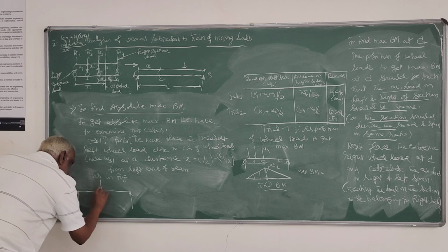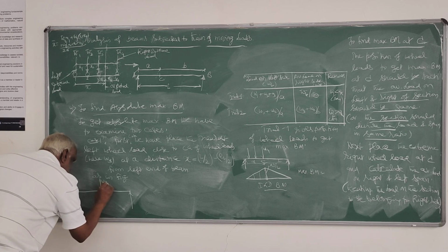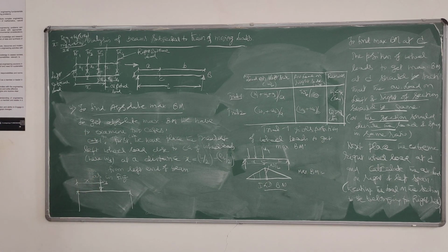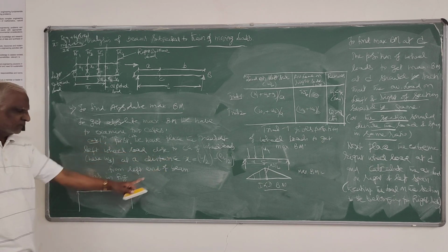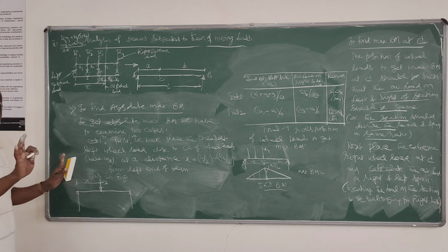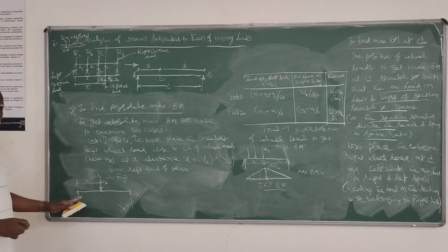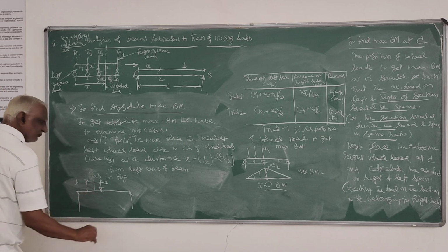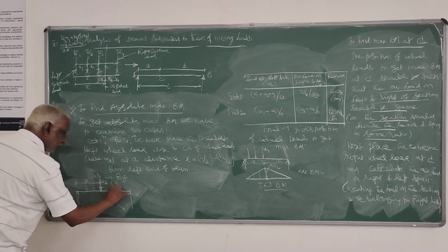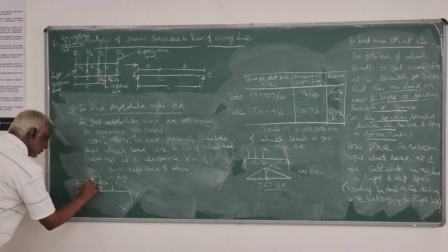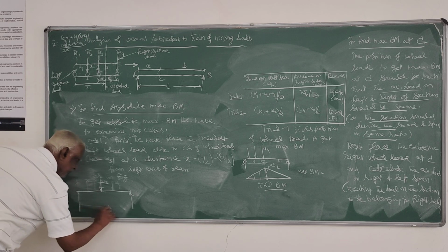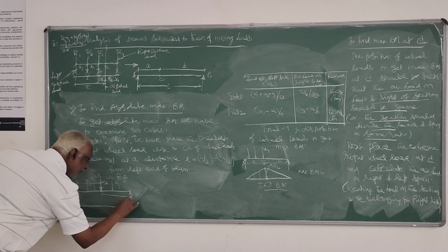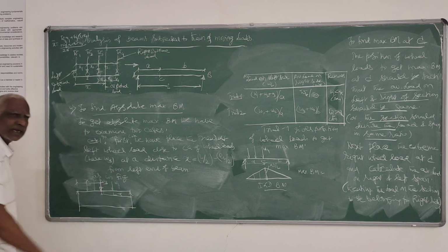So this W3, you have to place it at X. That X value we have worked out. Don't bother about that center and all those things now. So you place this, and then you place other wheel loads. W2, W1 will be here, W4 will automatically come here. For this position, you know this is X, this will be L minus X.